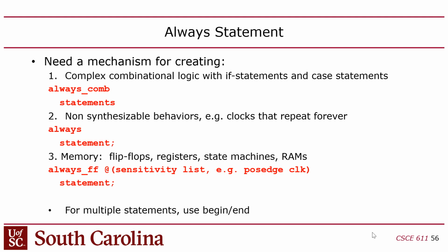So like you would say always, and then begin, and then end. And then you can say A equals, B equals, right? So you can do something like this, right? So in this case, the always statement, you think of it like an assign statement because it's now the driver for any signal that's assigned inside of an always, it's now kind of owned by the always block, right? Now you can assign it more than one time in here, but you can't assign it anywhere outside the always block because the always block now is the driver for A and B because you've assigned them in there. Does that make sense? Okay, so you can do that.